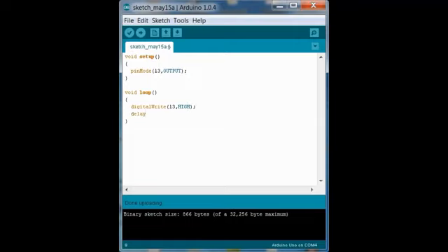Then we want to use the delay function, which takes inputs in milliseconds, so 500 would be 500 milliseconds. We want it to stay on for a while, and then we want it to turn off, and then stay off for a while. So we have it on, delay for 500 milliseconds, off, delay for 500 milliseconds, and it's going to loop through. That's where it's in the void loop part of the sketch. So, alright, there you have it. That's making the LED blink.